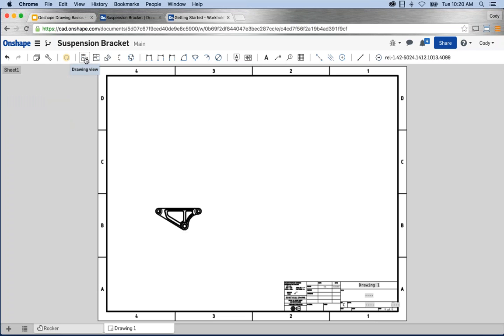But another way you can do this in the case of a top, right, and isometric, is they're actually projected off of the front. And the neat thing about projecting these views is that it links them. I can have things like the scale be the same amongst all three of them and change it all at once. So there's a lot of neat benefits to projecting a view. So I'm going to select projected view from the toolbar, and then I select the view I want to project off of. Then move the cursor in the direction I want to project, and that's an important thing. So if I wanted a top view, for instance, I'd move up. If I wanted a right view, for example, I'd move to the right. So in this case, I want a top view, move up, left click when you're satisfied with the location, and it places the projected view.